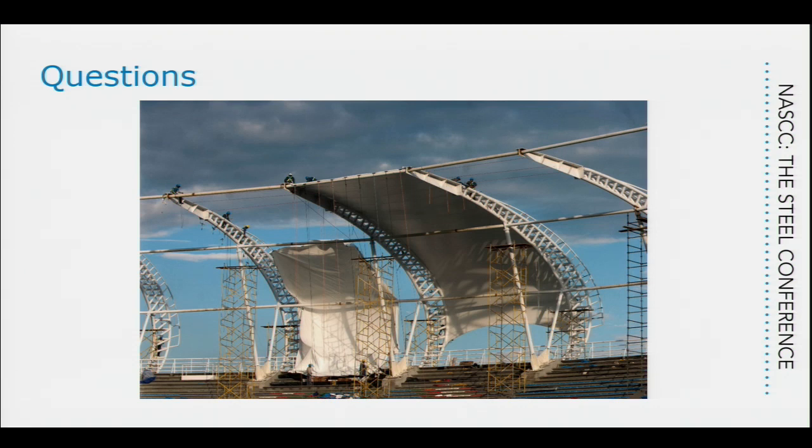Do they reinforce the attachment points? Because you said when the crane lifts it, you could rip it from a corner, because the stresses are supposed to be even along the edges. Correct. So the question is, do they reinforce the fabric at the point of lift? Yes. We establish a lifting procedure and say, okay, we're going to lift it from this point. Run the analysis. Can we lift it from that point? If the answer is no, we need to reinforce it, and what we usually do is weld an exterior patch to that membrane that is very strong.